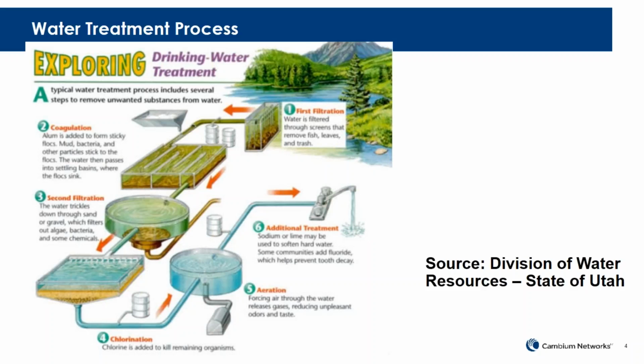And so what I want you to think about is that whole flow of water, all the way from that pond through these different systems, and that there are a number of things that have to happen. One thing is I want to monitor the temperature, the pressure, the level of water in each of these areas. I want to monitor how much water is flowing through each of these areas. And then I also want to be able to turn on and off pumps in these areas so I can stop the flow or start the flow at any point in this process. So traditionally you might do that with a bunch of valves, where you have to send somebody out to the field, turn the valve, take a look at how the flow is working, and turn those valves.